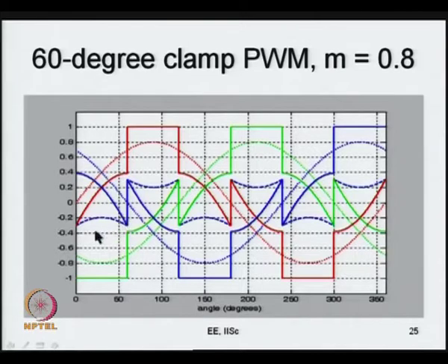Now what I am trying to do is, you see this blue signal, do you see this signal? This is the common mode. I am getting it by subtracting different modulating signals in different regions from either +1 or -1. Now, when I add this common mode signal, what happens? I get a resultant waveform like this. You see the red waveform? So it is clamping here.